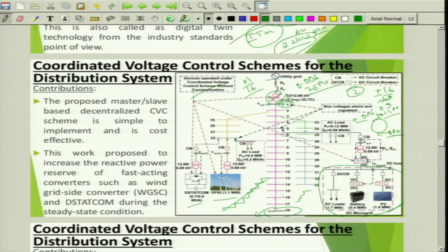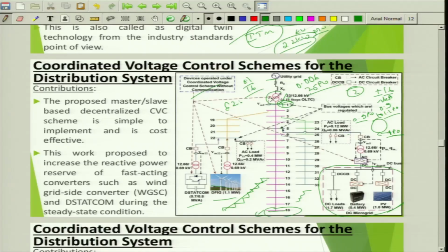So now you have multiple combinations, and OLTC has its own time constraint before it operates. It does not operate instantaneously. Of course, in this study we have considered electronic OLTC. It is not mechanically operated OLTC, but yet the simulation time would be in terms of 625 millisecond or something like that. The mechanically operated OLTC would take more time, in terms of seconds, 10 seconds, 12 seconds,